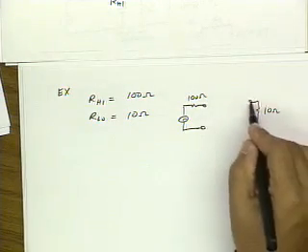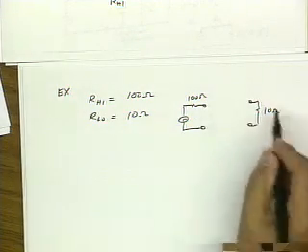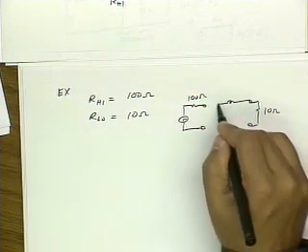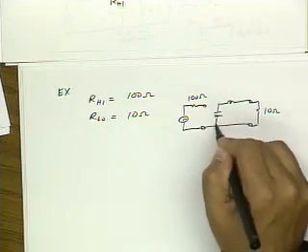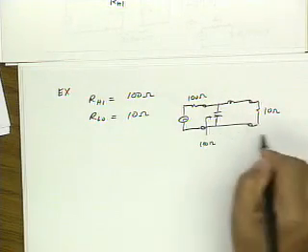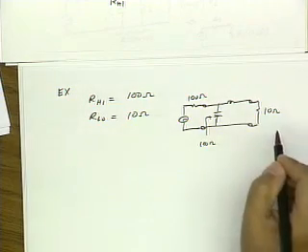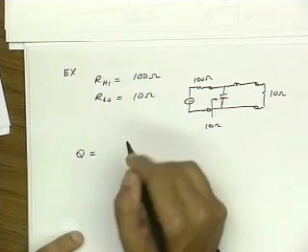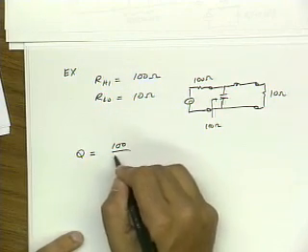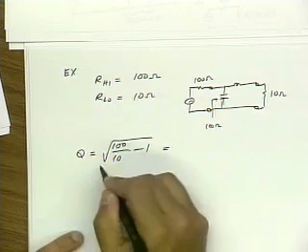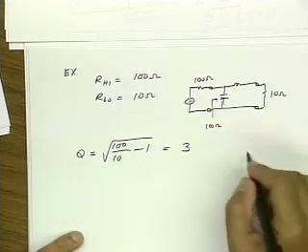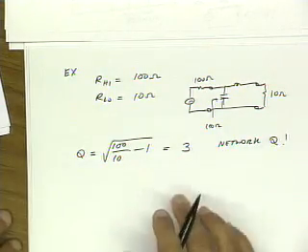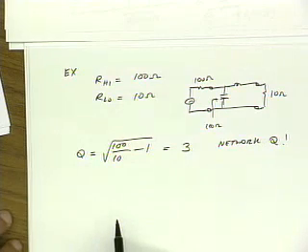Now, if I drive it directly, I'm going to waste a lot of power. I'm not going to be able to transfer the maximum power to the load. So what I'm going to do is put a matching network in here to make this 100 ohms, and then I extract the most power possible. I extract the available power. Well, the design equations are that the Q of the matching network is the square root of R high over R low minus 1, or 10 minus 1 is 9, square root is 3. So the network Q is fixed at 3 based on this impedance matching network.